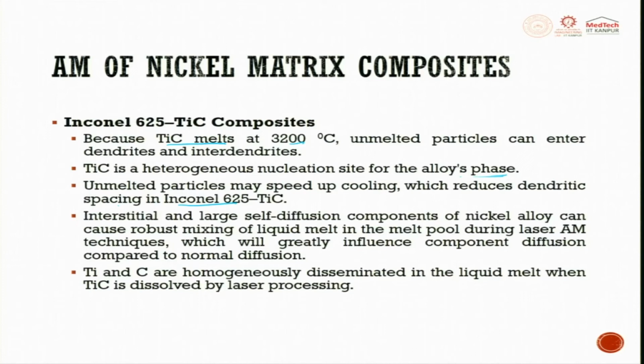Interstitial and large self-diffusion components of nickel alloy can cause robust mixing of liquid metal in the melt pool during the laser additive manufacturing technique, which greatly influences the components' diffusion compared to normal diffusion.